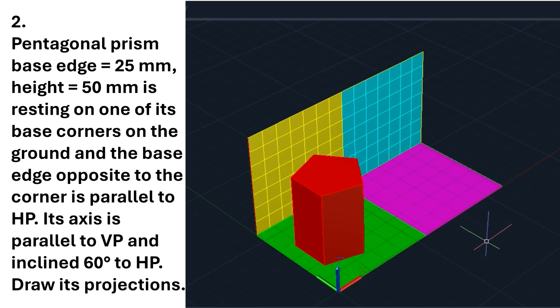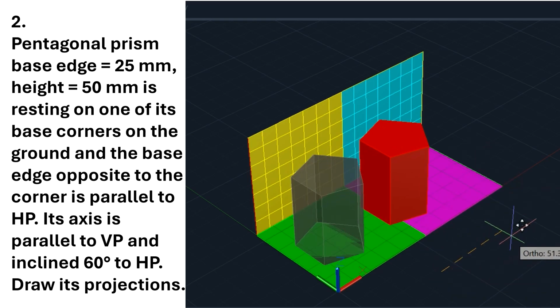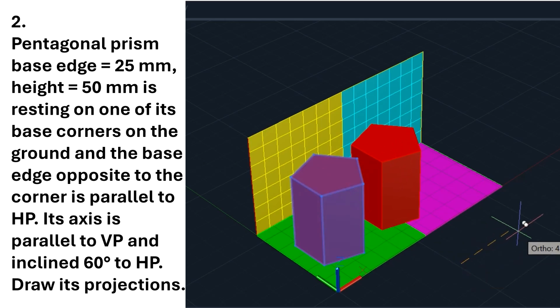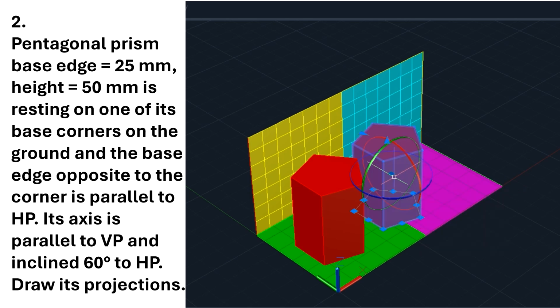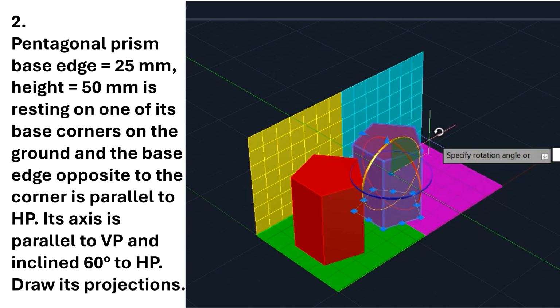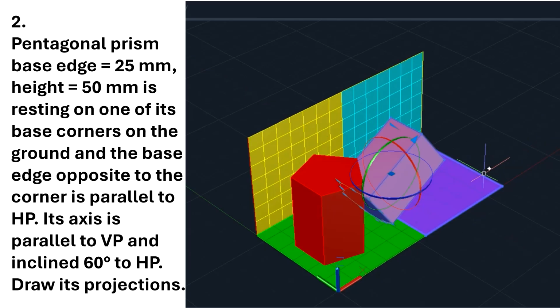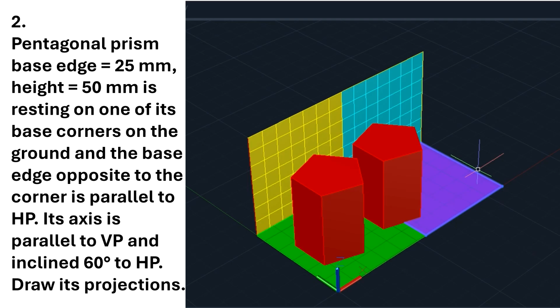I will draw the front view and top view of this, then I will rotate this solid to get the final view. So now I will copy for the second position. I will copy this solid and I will rotate this solid to 60 degrees. I will rotate this solid to make 60 degrees. So like this. So 60. That is already 90 degrees is there. So I need to rotate this.